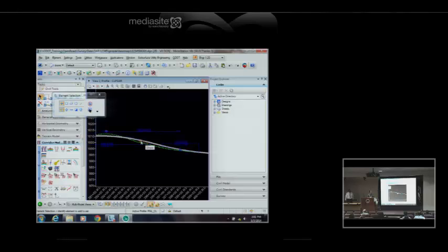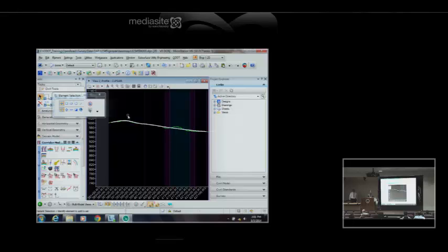But when I pick it, there is a different pop-up. Like it's a 700-foot vertical curve. I can click on that there, change the length to 600, update. So now it's a 600-foot vertical curve. Example of some of the in-place editing civil features there. Thought I'd throw that out there.